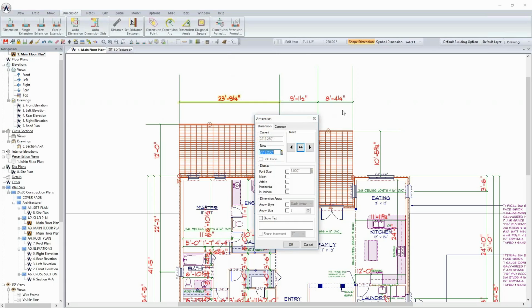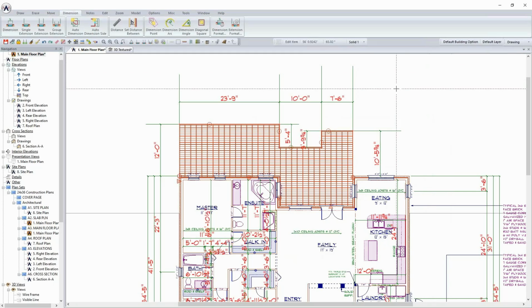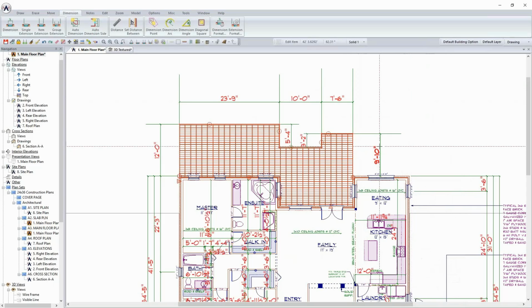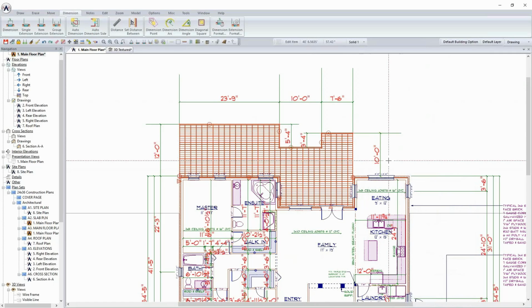Working left to right, in a similar fashion to how I would do a house, where I run left to right and oftentimes top towards bottom, I'll now just go in and key these dimensions in, removing fractions from the design as I go. Really, this part is just as it comes down to design, so to speak. So I will edit that one there, and then this one here, we can edit it, and I will make it, let's say, 9'10", which will also modify that dimension there. So let's maybe make this an exact, let's say, 10 feet, and just even it off. All right. I will run a cleanup, and I will run a save on my deck at this point. So those are my dimensions into place already on the deck, having laid it out.